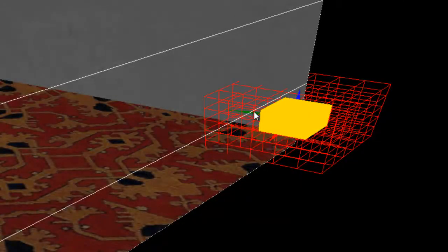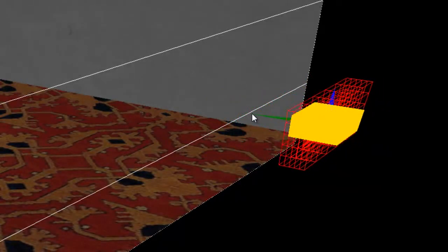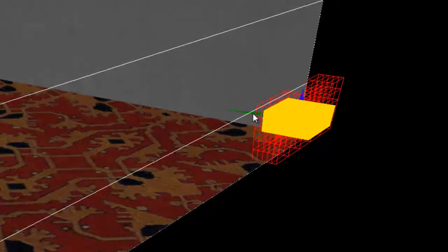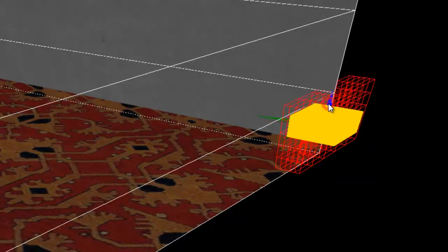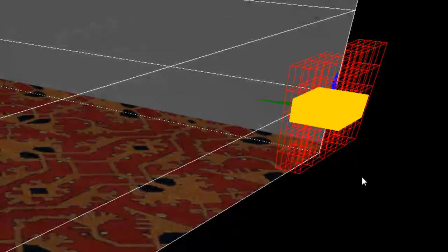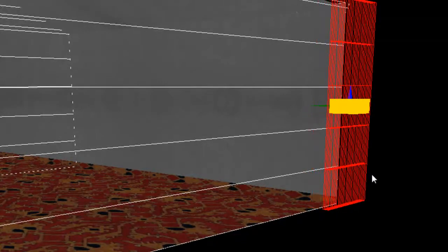Okay, and the collision's only going to apply where the object actually comes into the actual matrix of the object. So go ahead and shrink that collision box, and let's move it roughly to where the wall is. To do scale like I just did, you hold down the control key and then you can move it up and down using the mouse. Or you can also use the keyboard. In this case, I'm using page up and opening up that one.